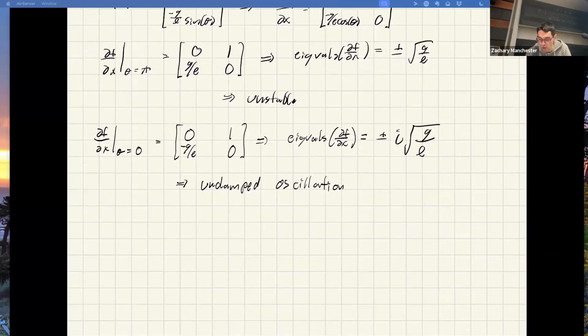But from our perspective, if you were trying to control this thing and make it stable, what you would do is add damping with your controller, right? So we can do that. We can literally use our torque input, our U, to shape the dynamics and basically make it act like there's a damper in there with the controller. I.e., we can make U equal minus some damping constant KD times theta dot. Just plug that in. And all of a sudden, that'll make us have pure negative real parts.